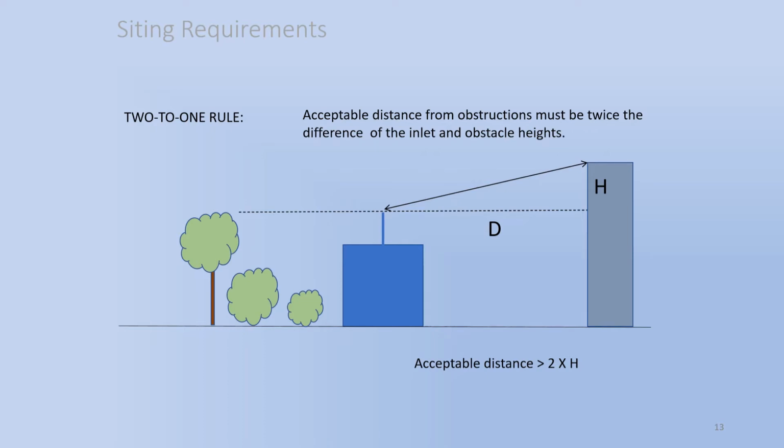For geometry fans, the angle in the resultant triangle works out to 26.6 degrees. The tree in this drawing on the left is at the inlet height, so as long as it's more than 10 meters away, for the drip line rule, it's not a problem here. But remember, trees grow. We'll see another example coming up in slide 22. These are simplified examples. However, keep in mind that the CFR includes criteria for the separation required between monitors, walls, parapets, and structures.